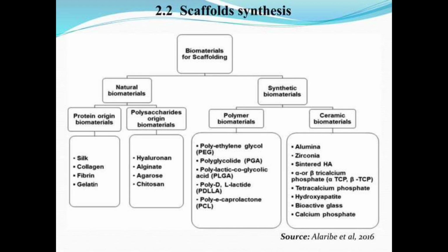The polymer biomaterials include polyethylene glycol (PEG), polyglycolic acid (PGA), poly lactic-co-glycolic acid (PLGA), poly-D,L-lactide (PDLLA), and polycaprolactone, that is PCL. Sorry. And ceramic materials include alumina, zirconia, sintered HA, tricalcium phosphate (alpha and beta tricalcium phosphate), tetracalcium phosphate, hydroxyapatite, bioactive glass, calcium phosphate, etc.